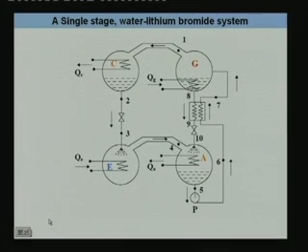So what we will be doing is applying a steady state steady flow analysis to this system to arrive at expressions for COP, mass flow rate, etc. Typically, in a steady state steady flow analysis for any refrigerant system, we take a control volume across each component and apply mass and energy balance for each component. Like that you apply mass and energy balance for all the components, and then you get a set of equations. Then you supply the required number of inputs and you get the output, as you get the properties from your inputs.